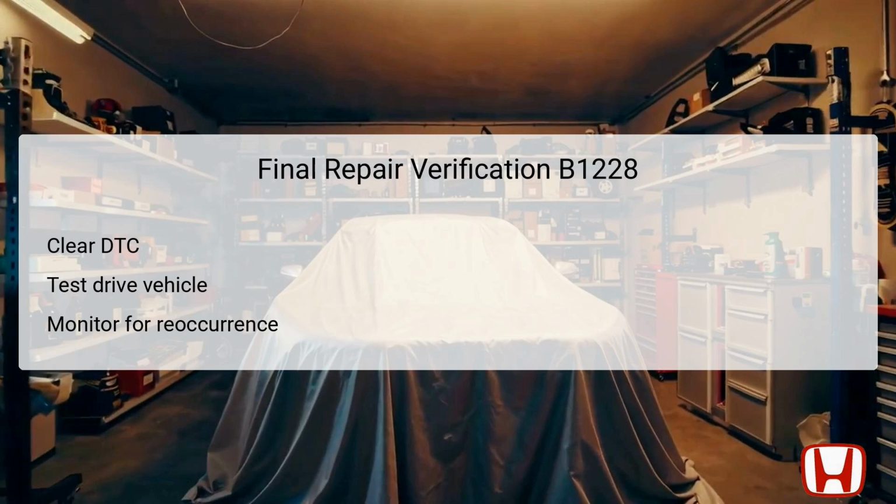After repairs have been completed, the final step is to verify that the repair has been effective in resolving DTC B1228. Begin by using the diagnostic tool to clear any active DTCs that were stored in the climate control unit after conducting the necessary repairs. Following this, perform a test drive under normal highway conditions to ensure that the climate control unit receives accurate temperature inputs from the outside air temperature sensor, allowing for effective cabin climate control.